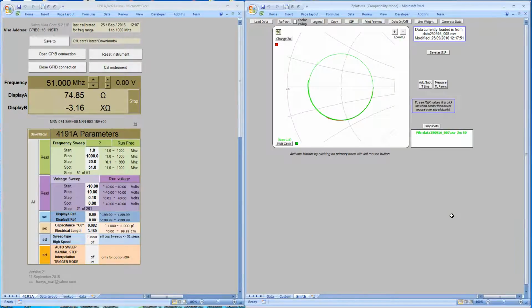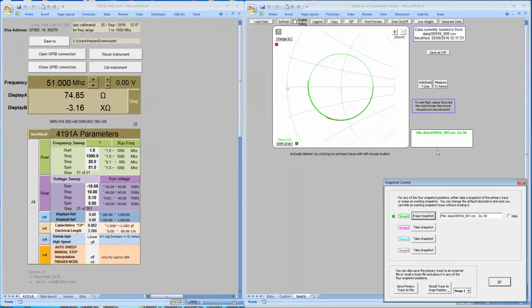And if I toggle the snapshot, you'll see the result. So you'll see, without entering the correct electrical length, effectively what happens is you rotate. You have a frequency dependent phase shift. So at 1 meg there's very little error, but as your frequency increases, the effective phase shift increases, and so the resultant error increases. So this is the correct result.